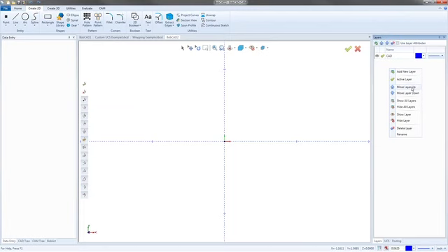For me personally, what I'll end up with at some point on almost all my drawings is a junk layer. And on the junk layer, I usually want that at the bottom. It's the layer I don't want to work with. And so what I do is I can now move it to the bottom, because sometimes I make it and it just doesn't work. So I just have to move it up and down. I want it at the right position, so I can move it based on these buttons now.